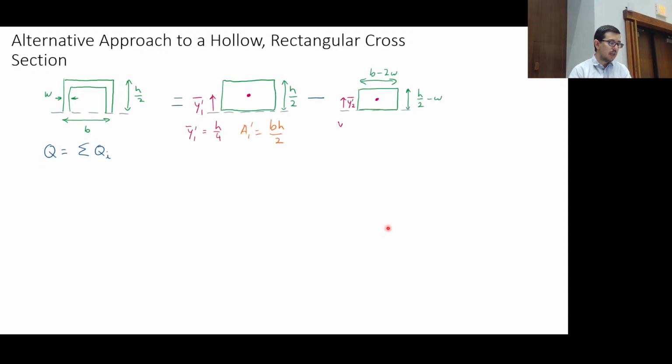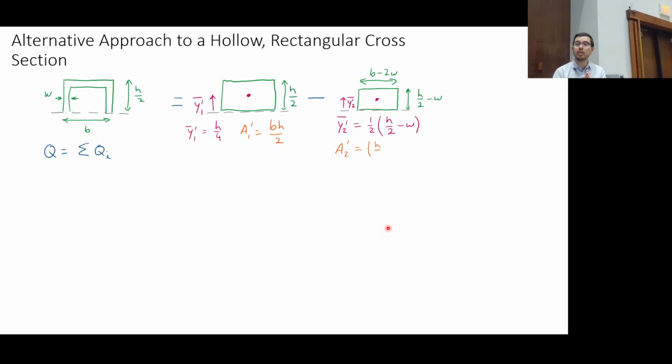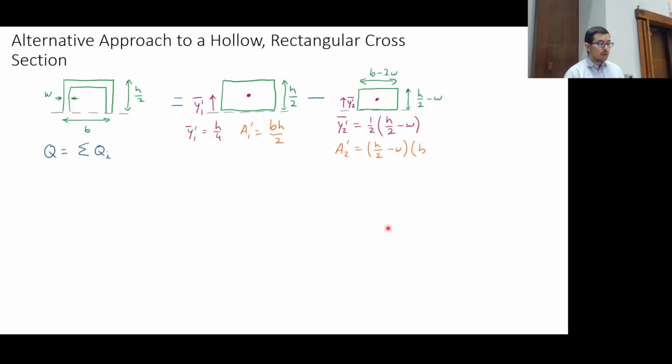But you can calculate the Q, and this is not super trivial, shall we say? Okay. And another way to think about Qs, that is less about doing the calculus with the integral and more about essentially subtracting, right? We know we could add and subtract the second moment of areas, especially when they had the centroid on the neutral axis.